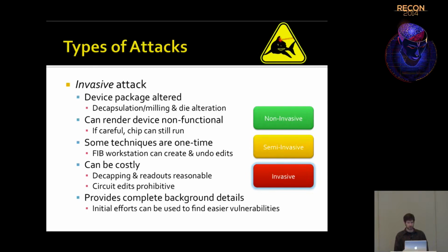You're pretty much using very scary acids that are stripping glass, basically. So the metal layers are coming off the chip one layer at a time, and you're going to destroy it, but you're going to image it in the process. Now, if you're careful, the chip can still run, not as part of the imaging process, but if you're just doing alterations and edits where you want to get to a certain data bus or address bus, for example, or a certain control signal, if you're careful with how you reach that part of the chip, it'll still run.